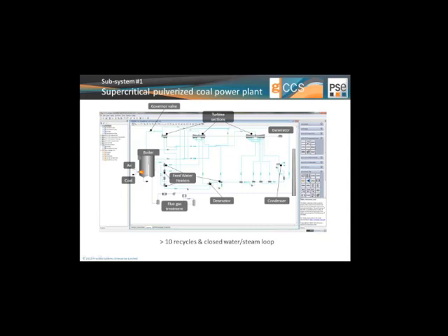The way that these models are used, in a first step, the user will calibrate the models to a given set of conditions. What we mean by calibrating is the user will be able to specify the inlet and outlet conditions, and for example, the system will calculate the heat transfer area of a heat exchanger, or in terms of a steam turbine, the internal parameters of simple models like the Stodola ellipse law constant.